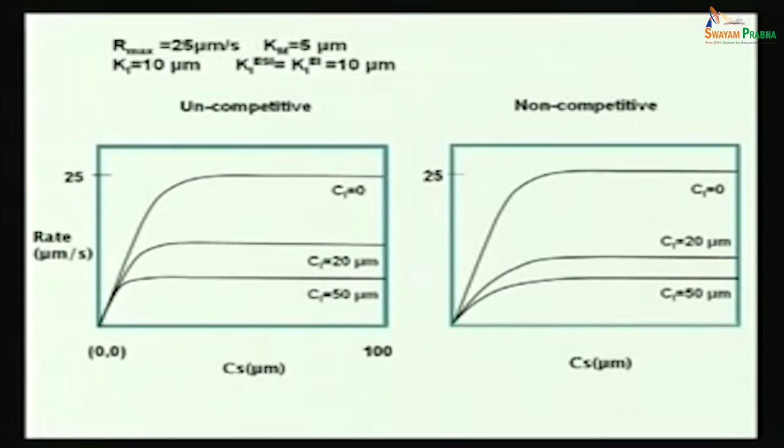Okay. So what will happen is that you can intermittently take out the product. Without changing the total residence time, you still keep the total residence time and the total reactor volume the same. But as soon as the product comes out as a mixture of product and reactant and other things from the first reactor, you take it out, pass it through a membrane separator unit, take out the product and recycle back the rest into the next reactor, and then you keep doing this all the time, right? Is it clear? So as a result, you will intermittently take out the product. So this is one way you can stop inhibition from the product.